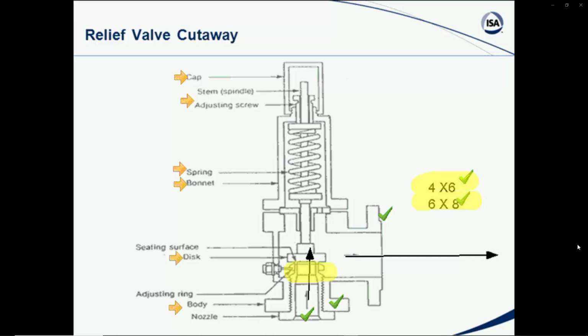We did the same thing on the control valve. It looks very similar. The relief valve body is basically like an angle control valve. Again, you have a variable orifice situation, a pressure reducing situation. The flow rate depends on the pressure differential across the relief valve. You can go to Ferris, Consolidated, Anderson Greenwood, Crosby, manufacturers' information and find these cutaways. You can find the materials of construction that are available, sizing information, et cetera.